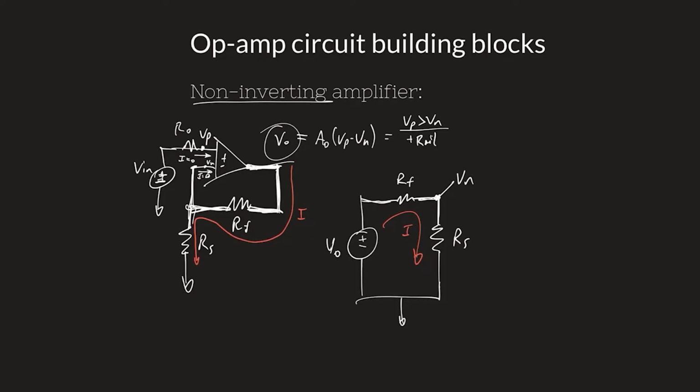If I hit the positive rail on this circuit right here, that's the highest voltage that I have available on this entire circuit. Because remember, the highest voltage and the lowest voltage are here. Those are my plus rail and minus rail, and those values determine what I'm getting on the output. So my output here, it wants to act like this.